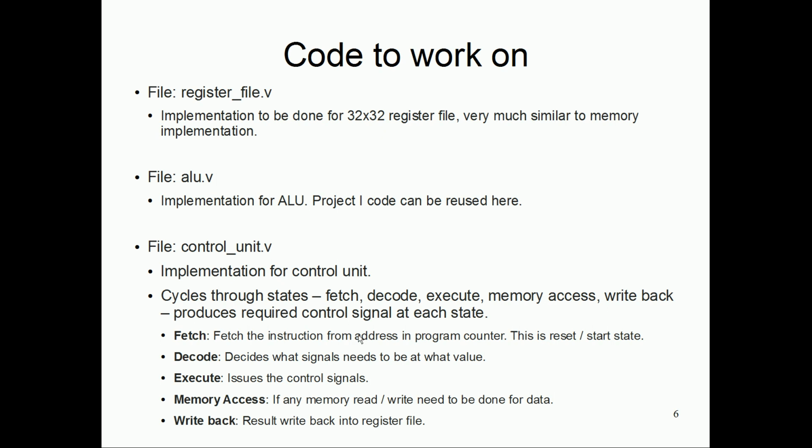In fetch mode, it issues the read signal with the address of the next instruction and reads it back. Decode is basically where you take the instruction value, parse the instruction code, and determine what needs to be done. Execute issues the control signals, and decode is also involved in that step.